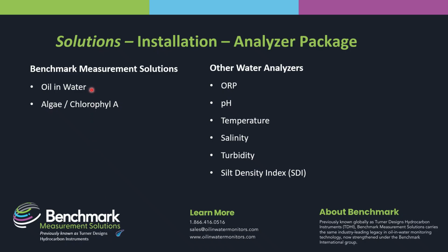What is unique for desalination with reverse osmosis is the fact that the oil should be monitored, or hydrocarbons or other fuels should be monitored because they can be significantly harmful to the membranes. Likewise, algae or chlorophyll should also be monitored because this is a seawater process we're looking at, and there can be fairly large blooms of both algae, bacteria, plankton, other things in the water.